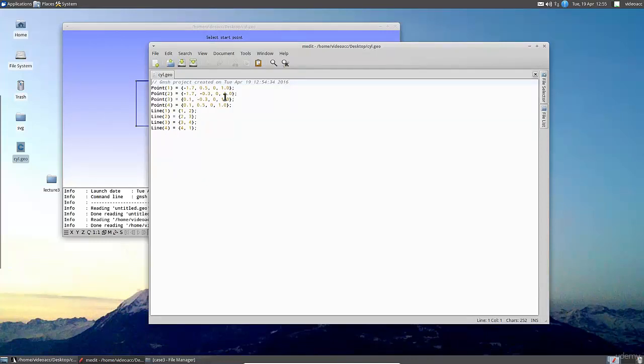Let's change the points a little bit. But first of all, let me create two constants, CL1, which equals 0.04, and CL2, which equals 0.005. Those are two characteristic lengths which we're going to use for refining the mesh. Let's change the first coordinate for point 1: 0, 0, 0, and for the refinement we choose characteristic length 1, so just type in CL1.